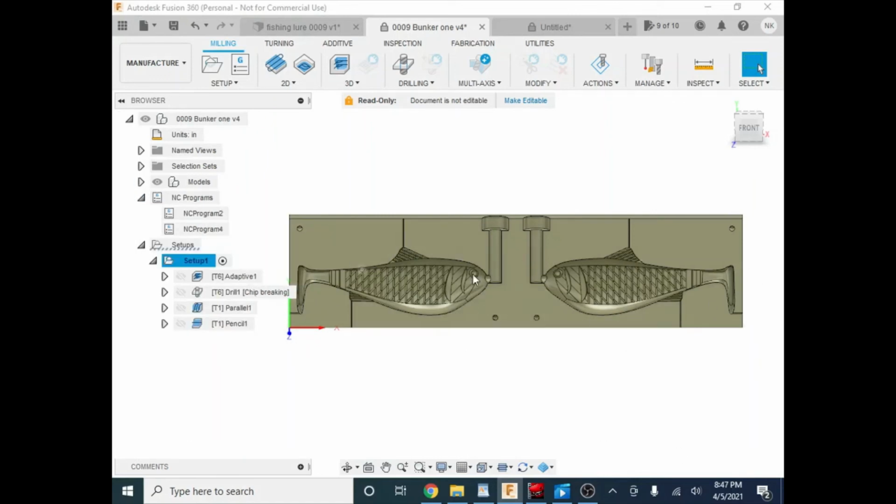And I set it up so I could just put this in the machine. It'll cut out both parts. And then what I did was I just took the bandsaw and cut this right in half. My indexing points automatically lined up both sides because they're positioned the same. And I was able to get one mold in one shot. And you can see all my extra air vents, all the extra details, as well as the entrance.